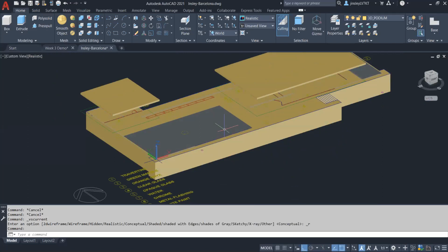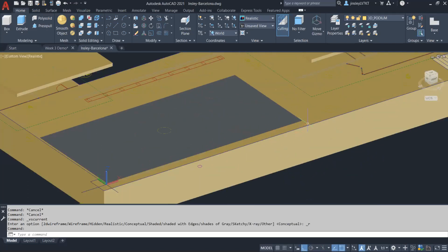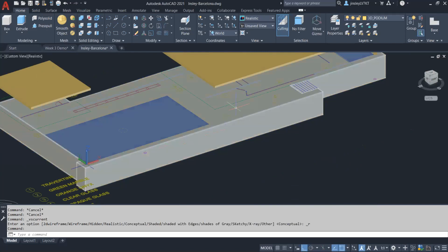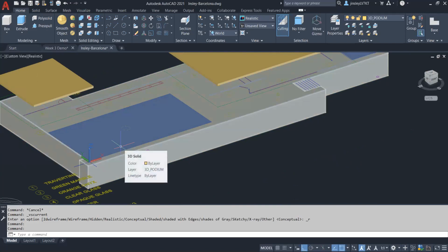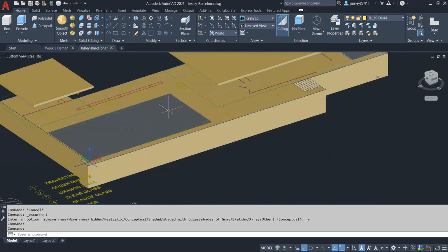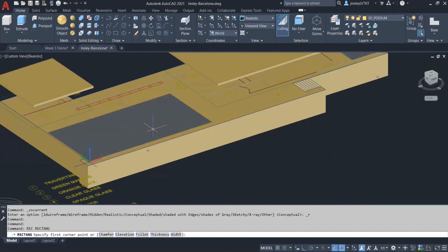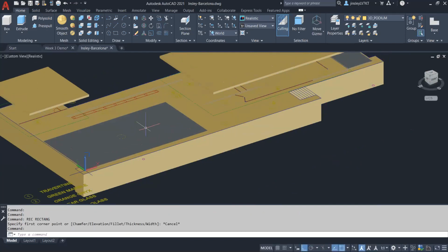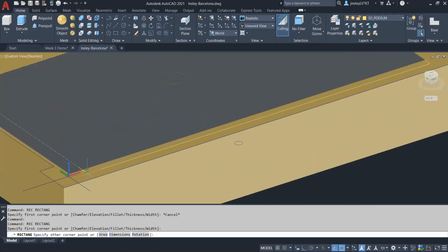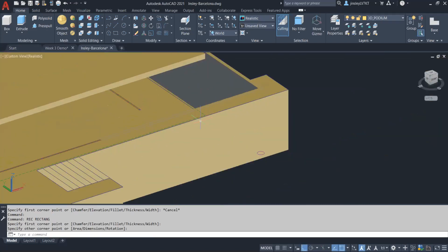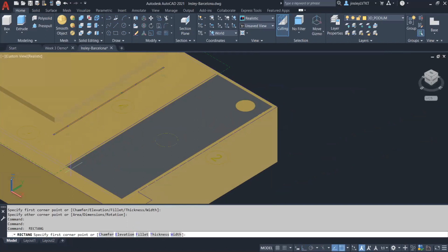Okay. So the thing I want to do is I want to do these pools. Okay, so you can approach it in lots of different ways. My way might be a little bit heavy-handed, right? But basically, I'm going to punch a hole through the entire podium, right? So if I go with my rectangle from one corner to the other, and do this side as well.